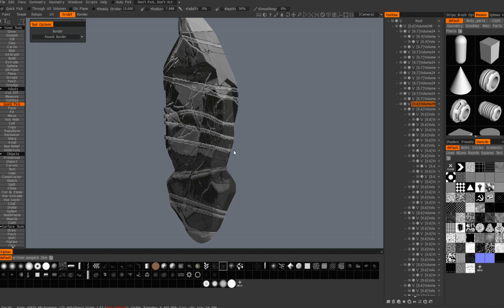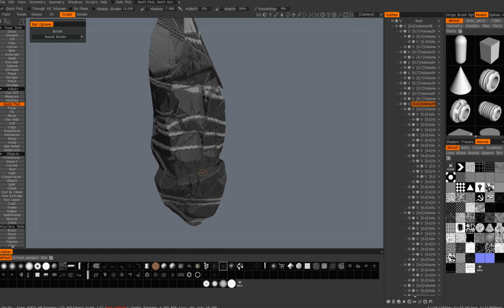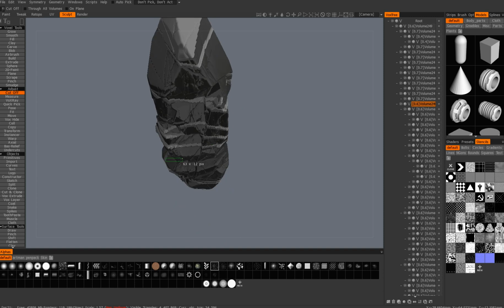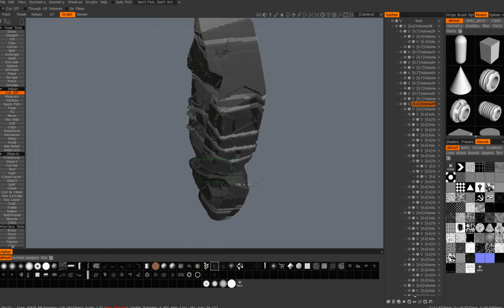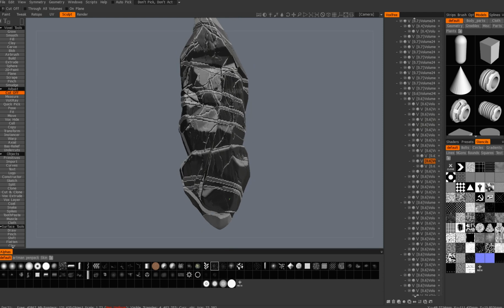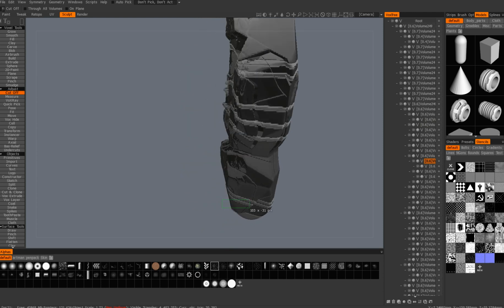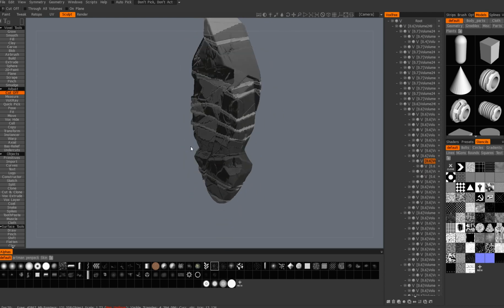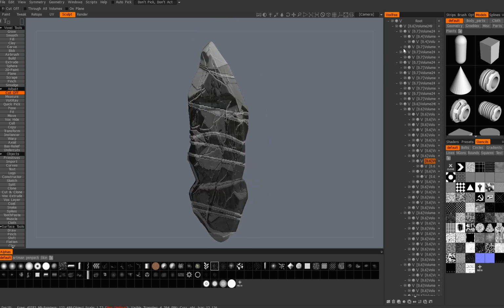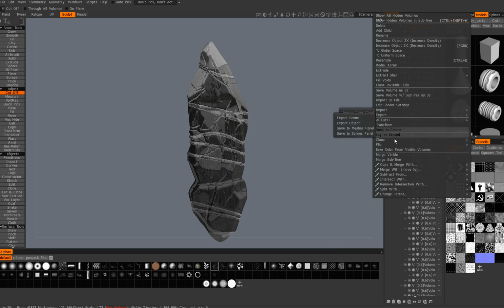Okay, just trying to figure out which layer corresponds to this particular cut. I think that one, let's do it and cut it inside. So the cool thing about high poly is you usually don't really care that it's broken into 1,000 pieces, right? You just want to bake it down. But if you want to export this as one solid model, you can just merge the whole tree. Let's save and merge it together. So I hit on the top layer and hit merge up tree.